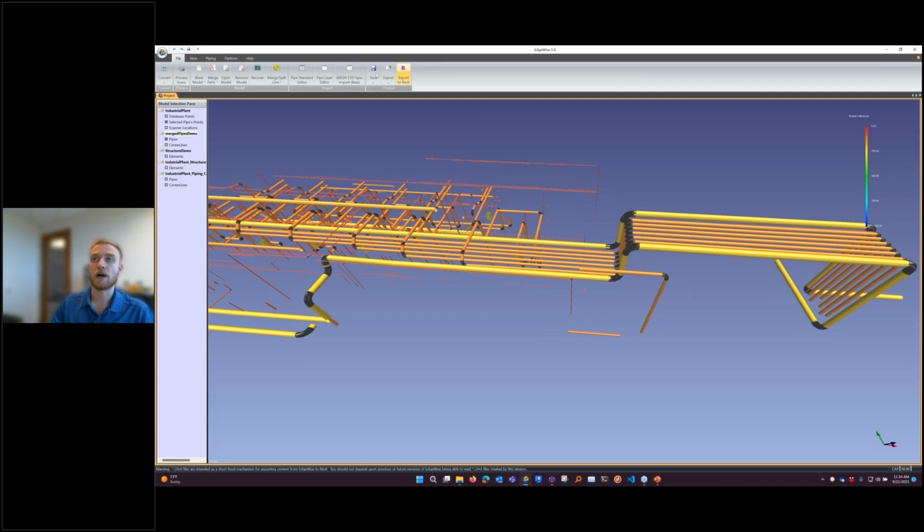And then in EdgeWise, we actually have a built-in function here where I can import those exported E3D catalogs, and then we will automatically generate an EdgeWise structural steel standard from the E3D spec, so that when I model in EdgeWise, it is native E3D basically components, like elements. So the steel frames that we're going to be making are based off of whatever the steel catalog is that you use. And so if you go through that workflow, you export the catalogs that you want to work with in your project, and bring those into EdgeWise, you model with those.